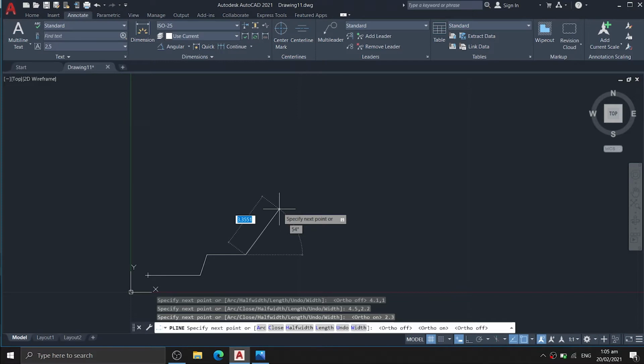When we subtract it from 180, we will get 30. And by this time, we will press the @ symbol for us to insert its distance and at the same time its angle. Given the values 1.4, tab, 30 degrees angle, then enter.